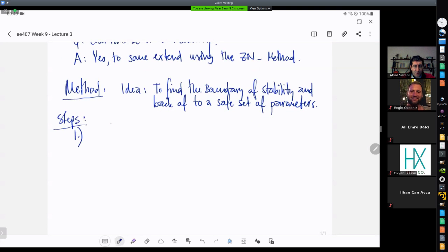You basically shut off integral and derivative control. Obviously, if you are working with a ready commercial controller, you can do this by either really turning off those modes of control, or you can play around with the coefficients to make these two terms vanish in the final controller formula.